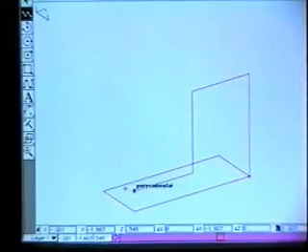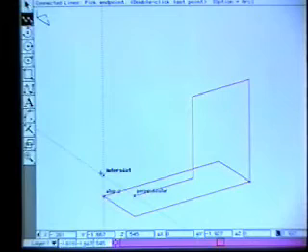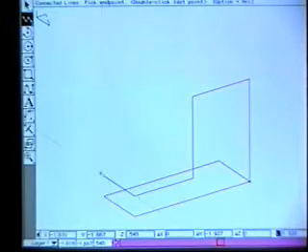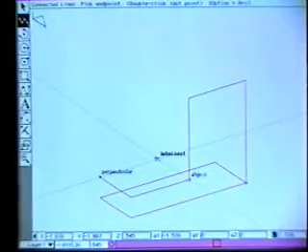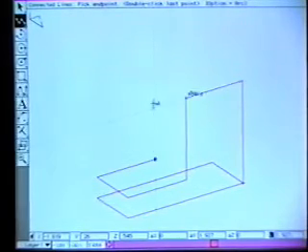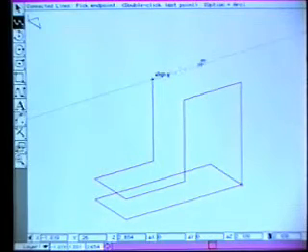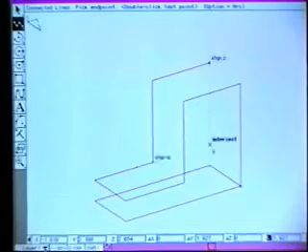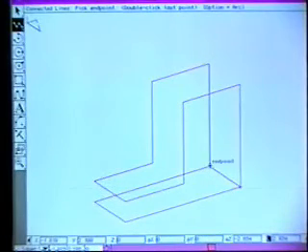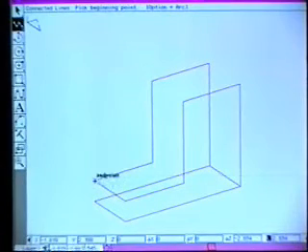But really what I want to do is go across now. So I can do an alignment like this, and here I have just the ability now to sketch loosely in 3D, and the drafting assistant gives me alignments in all three axes. So I can just pick out these points freely. And I'll actually go down now and finish the point right here. Okay. Now I will draw a single line segment over on this end.